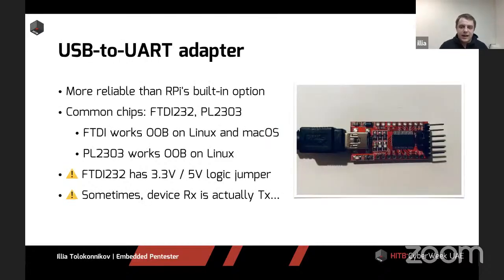Like I said, we use serial connection UART for communicating with a lot of our devices. And we found out that the pins on the header are kind of unstable. Maybe it was a power problem. But when we switched to USB to UART adapters, that problem disappeared altogether. So if you want some reliability, I suggest you use this approach if you go with a Raspberry.